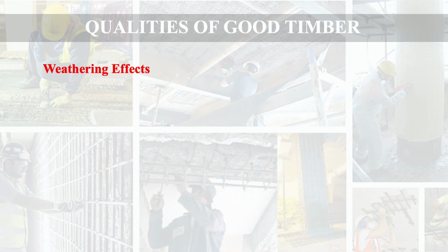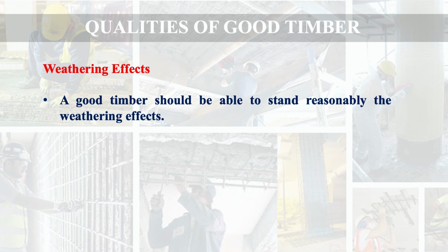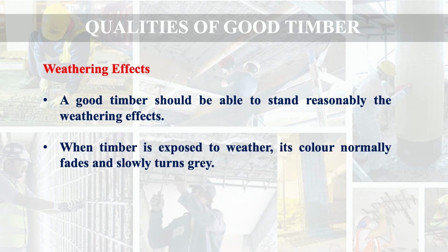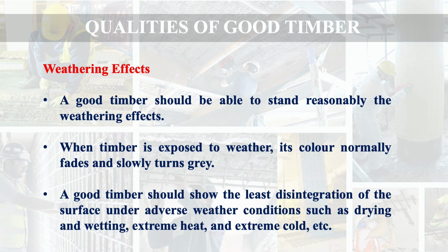Now, weathering effects. A good timber should be able to stand reasonably the weathering effects. When timber is exposed to weather, its color normally fades and slowly turns grey. A good timber should show the least disintegration of the surface under adverse weather conditions such as drying and wetting, then extreme heat, then extreme cold, etc.